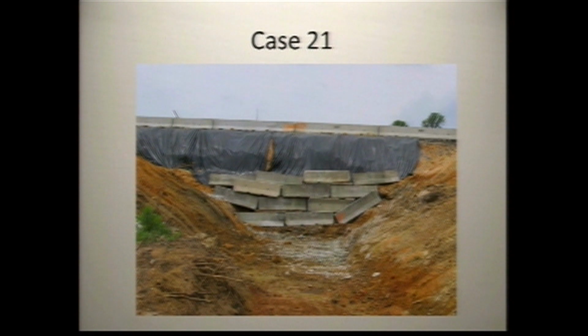This looks like it's going to be a conveyance, a flow path. So we need to have gravel bags in there to make sure that we're not going to get erosion, rilling as the water's flowing in there. You also see what looks like a lot of crushed up concrete. There's probably enough of it in kind of a powdery form where it's going to be a potential to have a pH problem. That's something that I would probably want to see cleaned up.